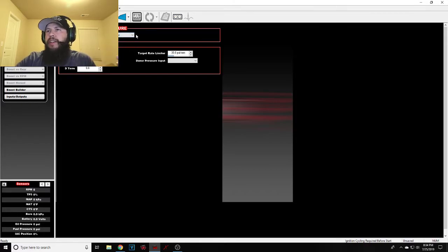Compressor is going to be if your reservoir is the turbo, or whatever means of pressure that you're going to be using. So in that scenario, it knows that it's going to be fluctuating based on the boost that you're building. So it gets kind of weird because you're trying to use this to modulate boost, but it's using the boost that you have to actually control.